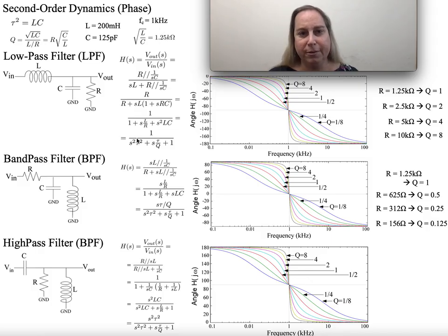One of the other things that's very important for any of these cases is this value of square root of L over C. And square root of L over C is actually units of resistance. Quite useful. You'll see this in lots of different cable and other electromagnetic stuff. Useful in a lot of places. But we'll start with that. And it turns out for this value it's going to be 1.25 kiloohms.